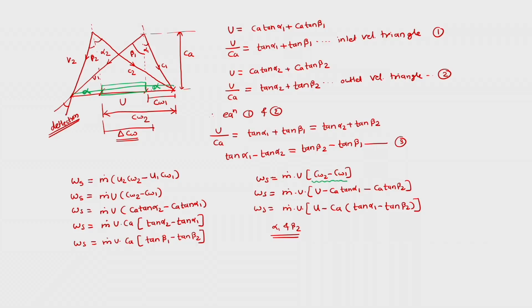So for that factor we wrote 3 equations for work interaction: one equation in terms of angles of the stator, one in terms of angles of the rotor, and one in terms of one angle of the stator and one angle of the rotor. Having said this, we would now calculate the temperature rise in one stage of the axial compressor.